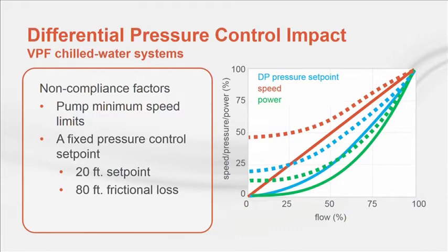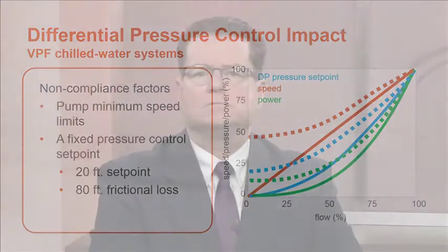It bottoms out at a minimum of about 9% of design at no load. 9% at no load is not huge, but it is much higher than the affinity laws would predict. What is more concerning is that the pump power is higher at all system load points. There are optimizing control methods to reduce this penalty, but that's a discussion for a different day.